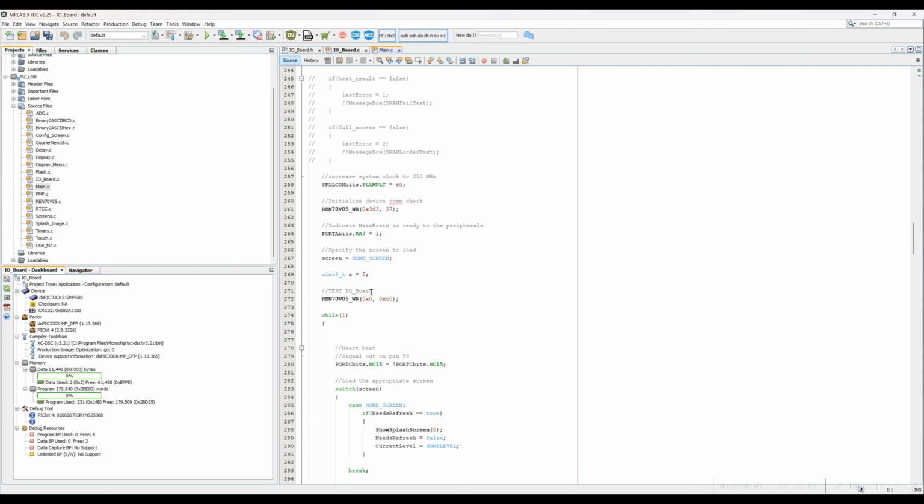So here's the test I/O board. We're doing just a test, and we're writing to this location, memory location 0, and we're writing the hexadecimal value C0 to it. And just one time. At the end of all our initialization, we just send that out there and write to the SRAM. And that's the only thing that MainBrain does right now in relation to our I/O board. So we can change this, and maybe we'll do that.